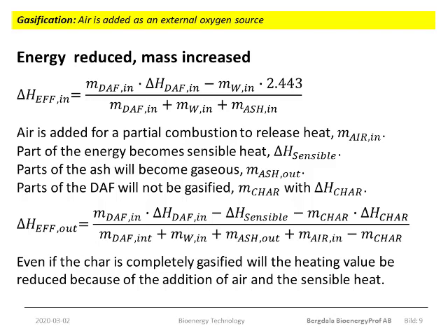So, very simplified, we can say that there are three general gasification technologies. Low heating value gasification using air as an oxidizing agent. Medium heating value gasification using oxygen-enriched air. And then high heating value gasification using pure oxygen and maybe also water vapor as oxidizer. But the thing is, and what I want to demonstrate with this example, is that fuel quality is not something uniquely defined and easily determined.